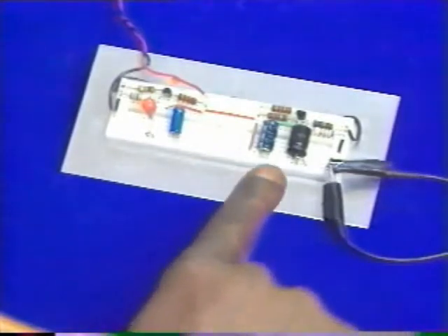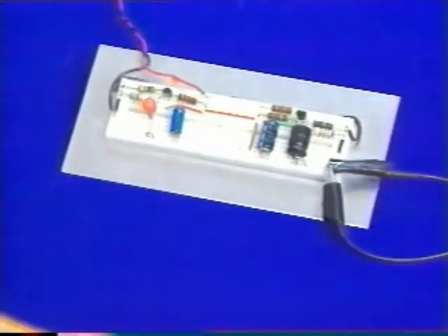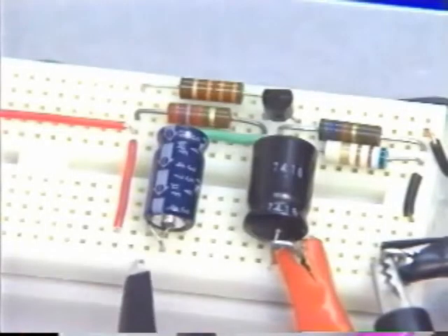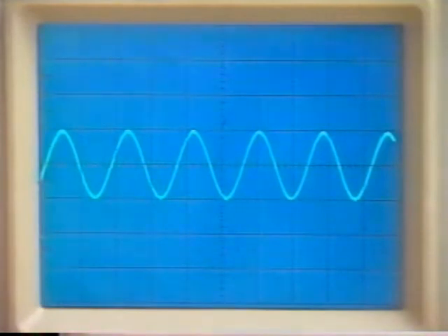Let's explore some real effects of output resistance in the same two amplifier circuits. The circuit on the right has a high output resistance, and the circuit on the left a low output resistance. The right amplifier has an output voltage of 1 volt peak to peak, which is 2 divisions at 0.5 volts per division.